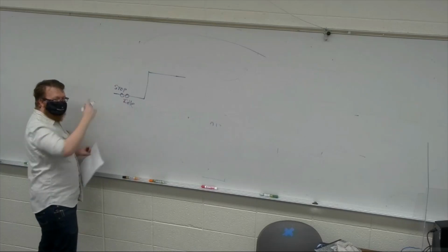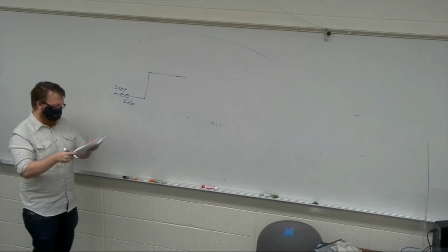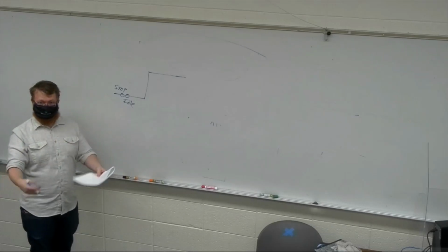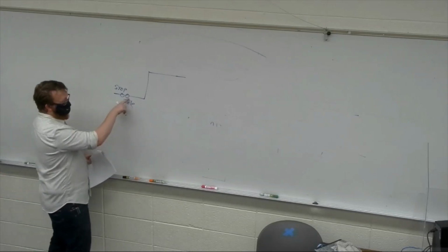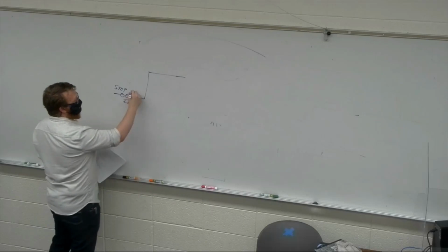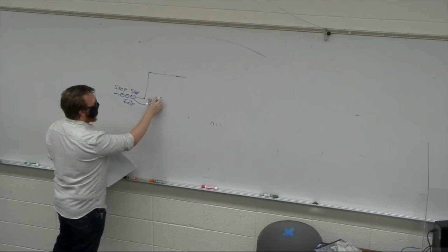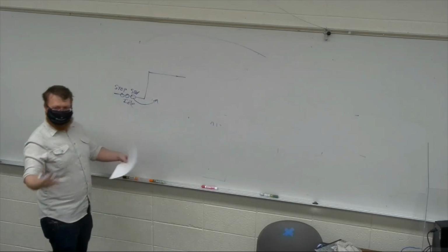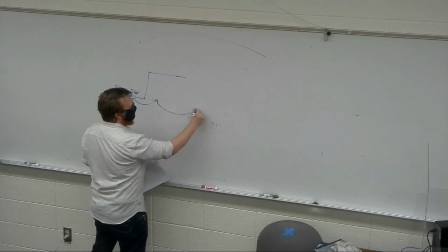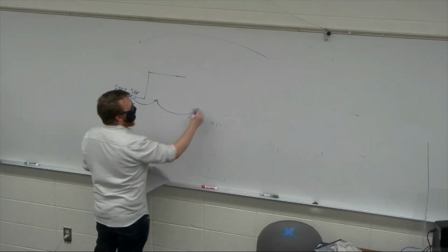Once I enter idle, what is the condition in idle to leave idle? We go back and look at idle, and idle says, if S data is 0, let's start receiving another bit. This is exactly what mine was doing. So 100 megahertz clock cycle later, it's right back into start, where it waits half a clock cycle for the stop bit to be over, to center itself. Then it waits 1 full clock cycle in order to take the first bit, so it waits here and then samples.